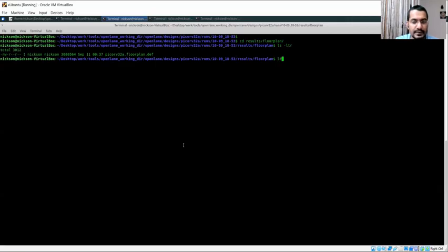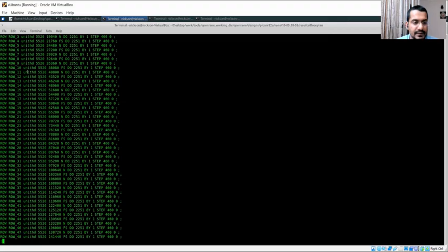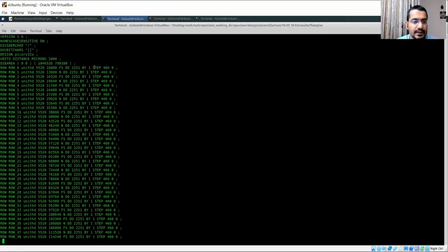So if you open this def file, you can see all this information. It says that this unit HD, this is the place site, it has been placed in this orientation at this location. So at the beginning of this def file, you can see something called a die area. So this basically is the area of your complete die.